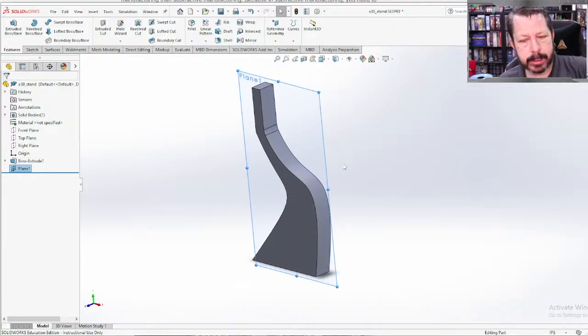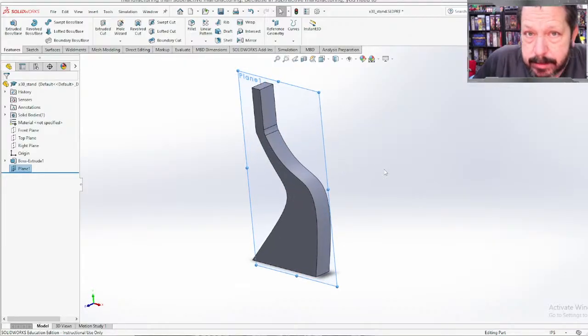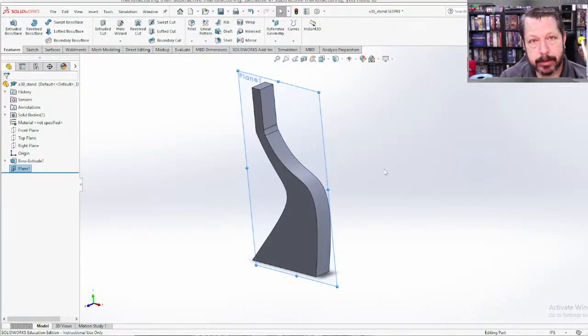What I want to do with this plane is, part of this process could be that I want it to be symmetric, or left and right, or up and down, or whatever. I want it to be nice and even on both sides. Otherwise, it may not do that. It might create uneven geometry. You know, the front side is different from the back side, but I want them to stay the same. Plus, technically, it'll make it run a little bit faster because it's only having to simulate half the model.